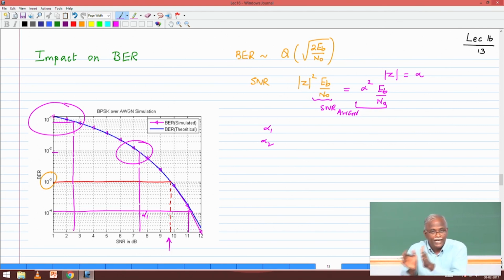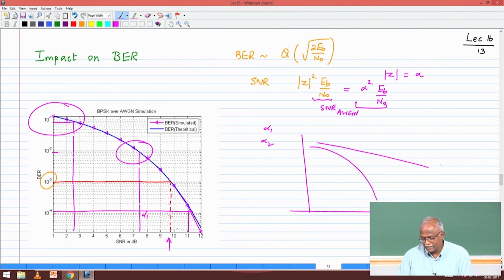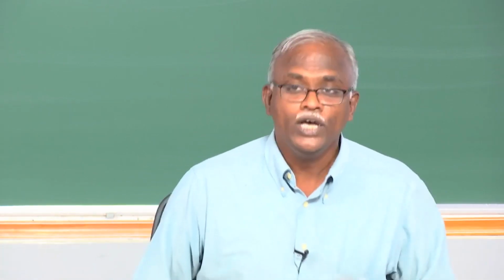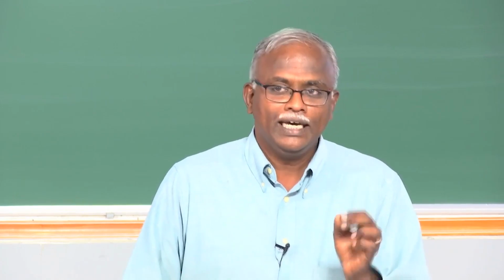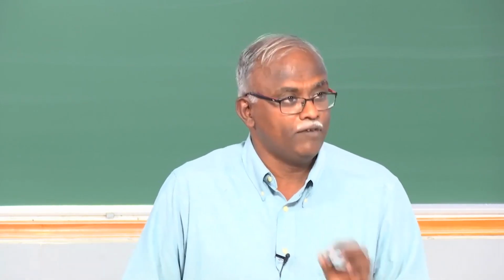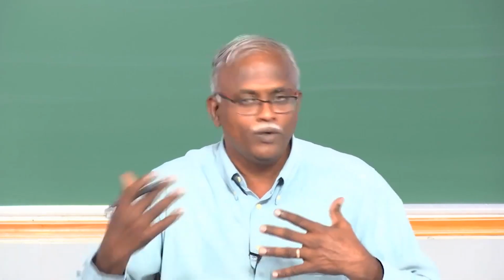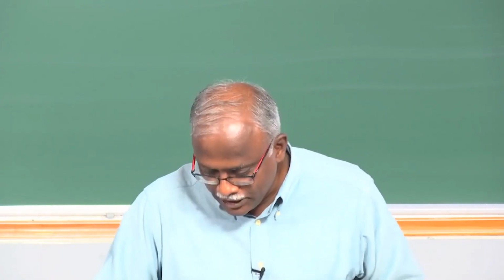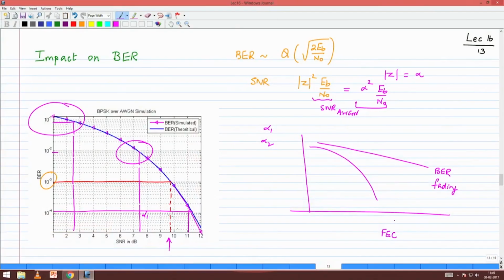It's just that from AWGN I moved to a fading environment, and then you ask me to look at the BER. This is AWGN BER. The BER in fading is this. BER in a fading environment, it is much, much worse. It takes a long time to even hit 10 power minus 2. Which means that I actually am working in a very, very error prone environment, and therefore I have to pull out all the techniques that I know in digital communications, FEC, equalization, all of the elements that I know, because this is going to be a huge challenge for me to solve.